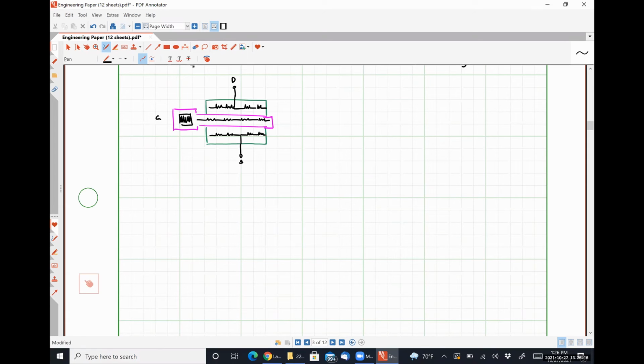So the active regions are typically on the order of tens of ohms. The polysilicon regions are typically on the order of hundreds of ohms to thousands of ohms if it's high res poly, right? So generally speaking, the active regions don't really contribute enough noise to worry about. The channel noise is going to be much, much greater than that, okay?